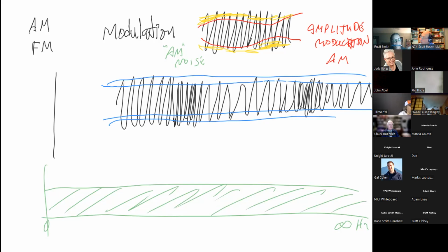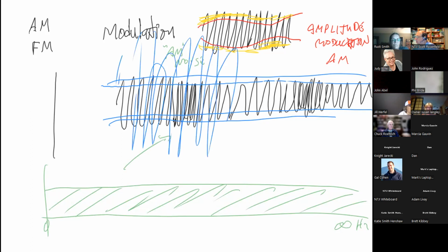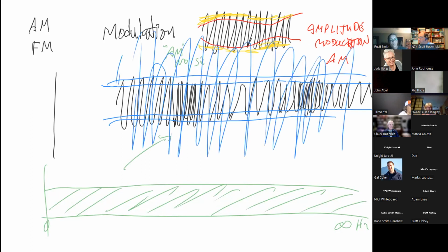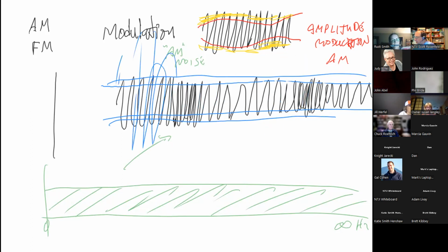Well, if I'm looking at FM, okay, so what? That basically means that my whole signal for a very short time is just going to be bigger. And by the time I get it into my transmitter, I ignore it anyway, which means that, as they discovered in the 1930s, FM is immune to noise. That's why FM is immune to noise. That's why people like doing FM radio. It's a lot quieter and cleaner than AM radio.